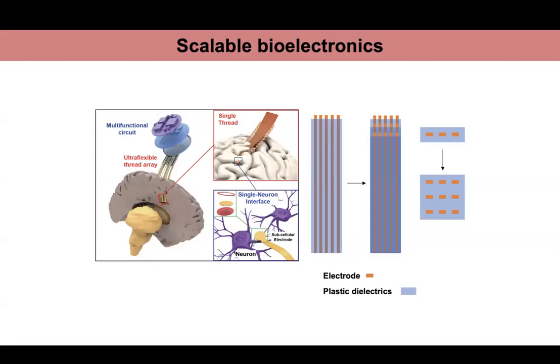But because we are limited by the materials, while for the interconnects, the electrodes can use nanometer thick gold or platinum, it will not contribute too much to the mechanical rigidity. But the dielectric material, that is the material used to encapsulate the channels from crosstalk or prevent the leakage current from each channel to the solution, cannot be further reduced.